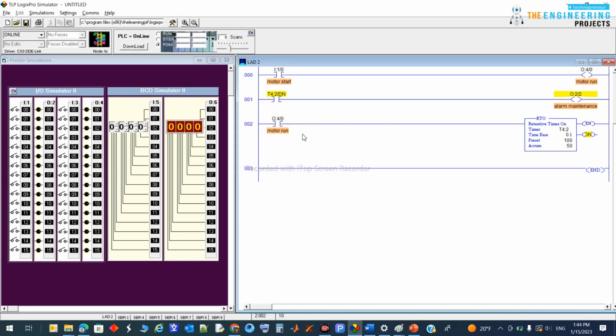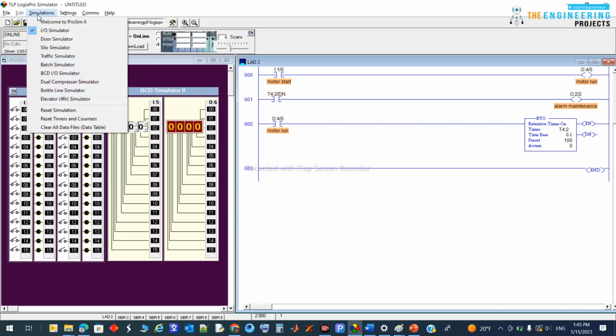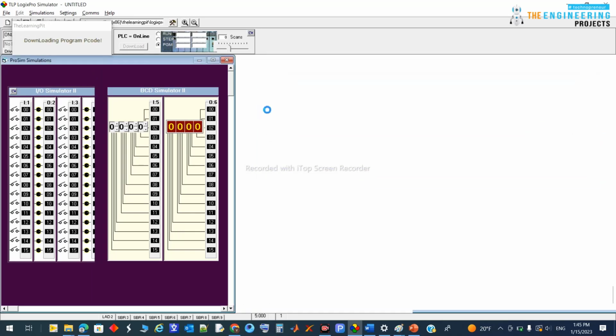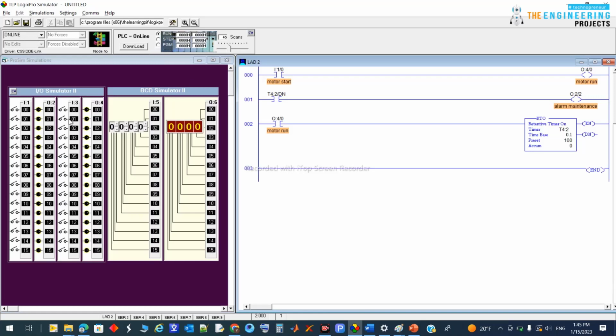you can see here, guys, this retentive timer counts. I need to just reset the program. Because of a conflict in the simulator, I just click here, clean all data. Okay, for now the timer accumulation is 0, and I set the preset value to 10 seconds. I downloaded the program, moved to run, hit this one and then off again.